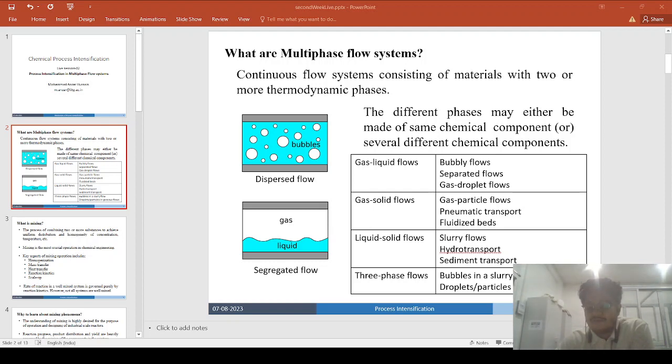So at identical values of pumping power and pressure drop, in the literature it can be found that the zigzag channel outperforms the straight channel by up to a factor of 6. So for the same pumping power and the same pressure drop, a considerably higher heat flux is achieved in a curved microchannel. This is a very interesting result in view of the design of micro heat exchangers, where the goal is often to increase the heat flux while limiting the pressure drop.